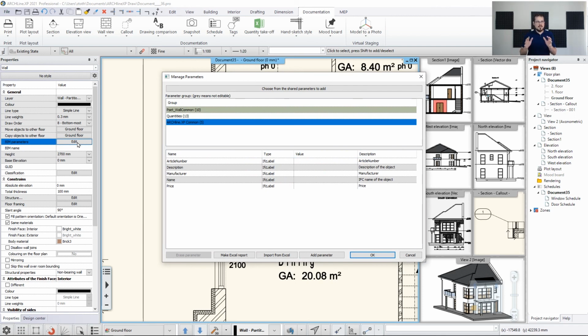So whenever you have an item, any kind of item, doors, windows, objects, roof layers, etc., this is where you can add information bits, additional data fields, which would be the building block of building information modeling. And later on, when you're making an export, either into IFC or into an Excel, these information bits would be retrievable. That's just a short detour. But if you want to ever work in BIM, then you need to know that the basic building block is information, and this is where it is stored in ARCHLine.